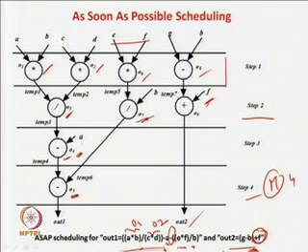So, we have to take the maximum one, because O7 is already scheduled in time step 2, but another dependency of O5 is O4, which is done in time step 3. So, you have to take the maximum one and add 1 to it. So, 3 plus 1 is 4 and O5 is scheduled in this step. So, in this way we get the as soon as possible schedule.